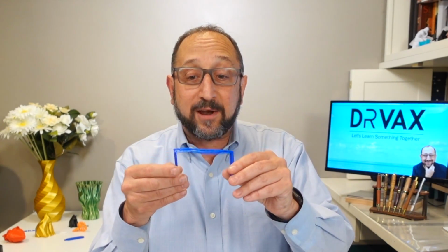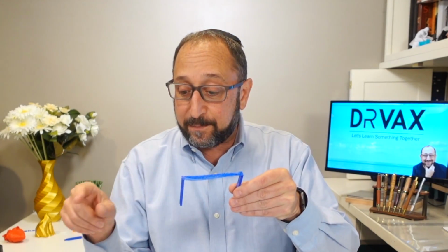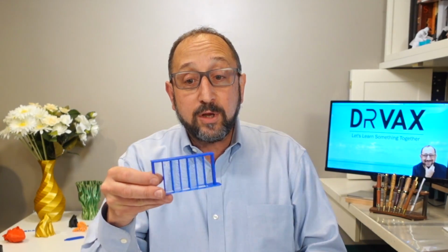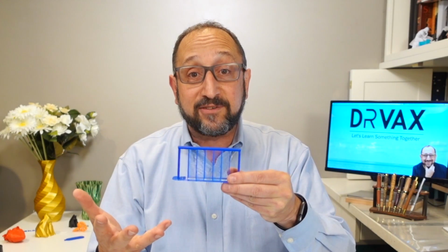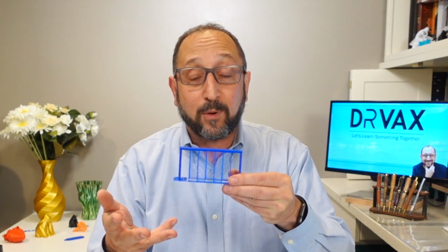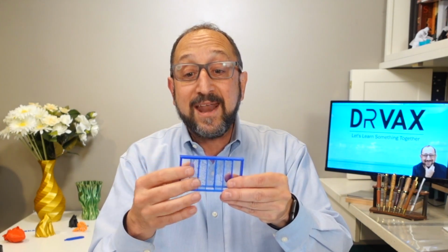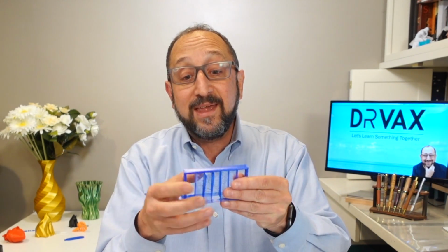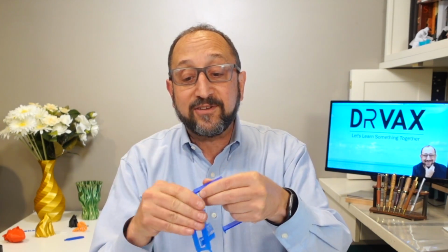Just as a bit of background, supports are used when you have a model such as this model here, which is not supposed to be flexible. That's because the top layer did not print properly, and you want to be able to print it. So you need to add additional structures underneath, and your slicer adds those automatically. Those are called supports. There are many options for these types of supports, and depending on how you add them, the supports are easy to take out, as in this case.